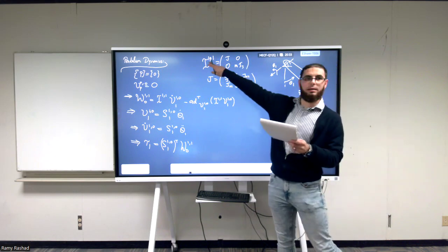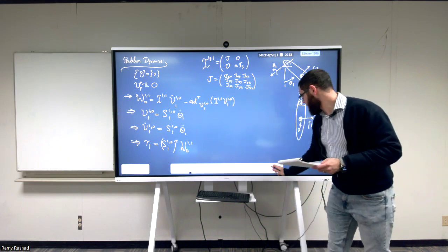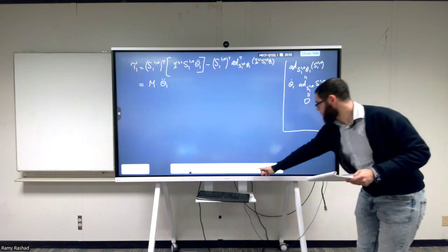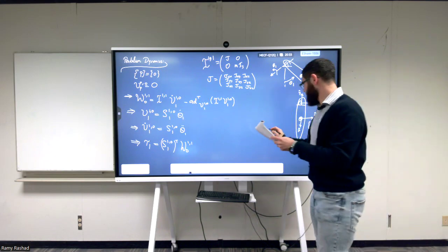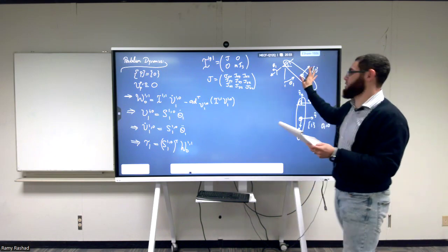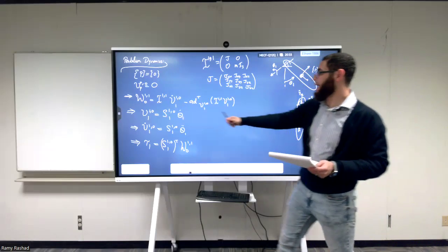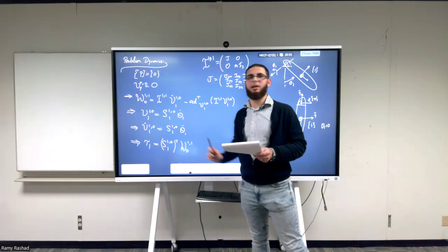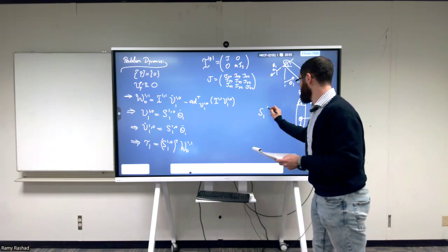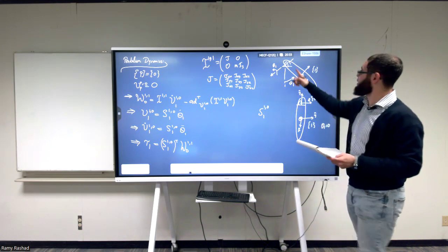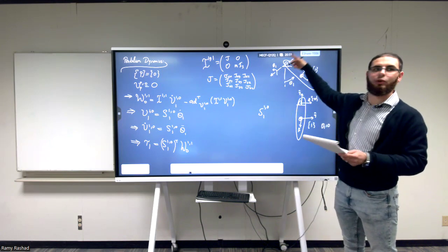And then multiply the I by the S, which in this case we haven't defined yet. So what is the S? This is the only thing we need to define as a constant here for this to work out. What is the S of 1 with respect to 0 expressed in 1? This is the screw axis we were talking about.